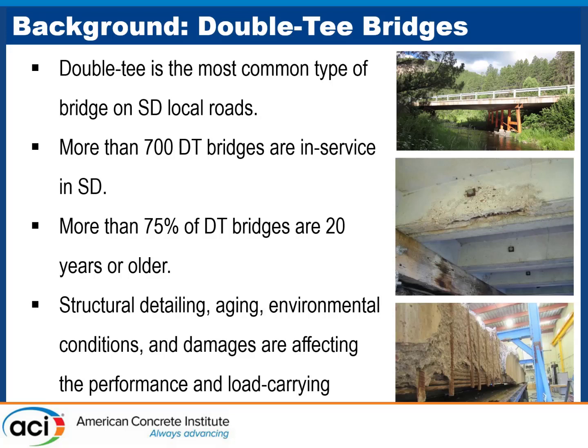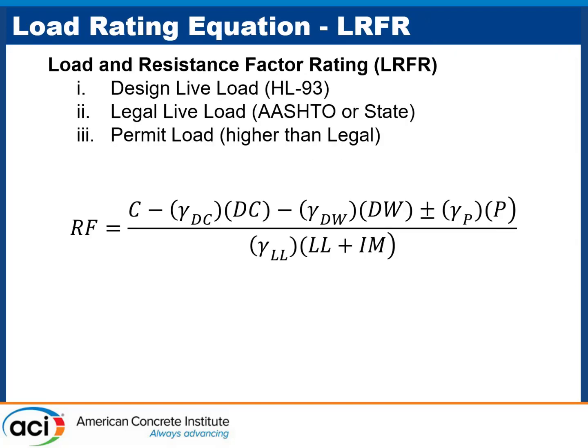And we have seen that 75% of our bridges are 20 years old and older. They should live 75 years. They are not. We are changing them at 45, 50, mainly because of a lot of damages that they get, and especially in the longitudinal joints. You see a few common damages that we have, and I showed them here. Okay, the big challenge was